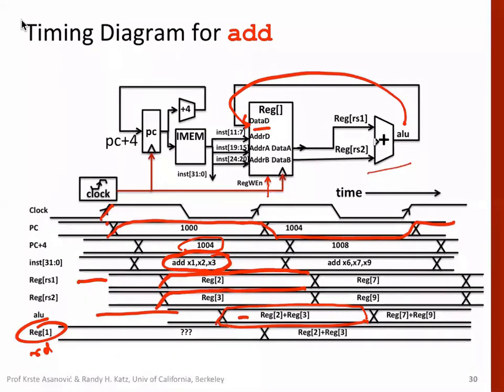So what happens is that this destination register will be written only at this clock edge. So this value that's available here, the summation of whatever we have read from here, will now be written into register RD. So the RD value change is available here now. Is it becoming clear?